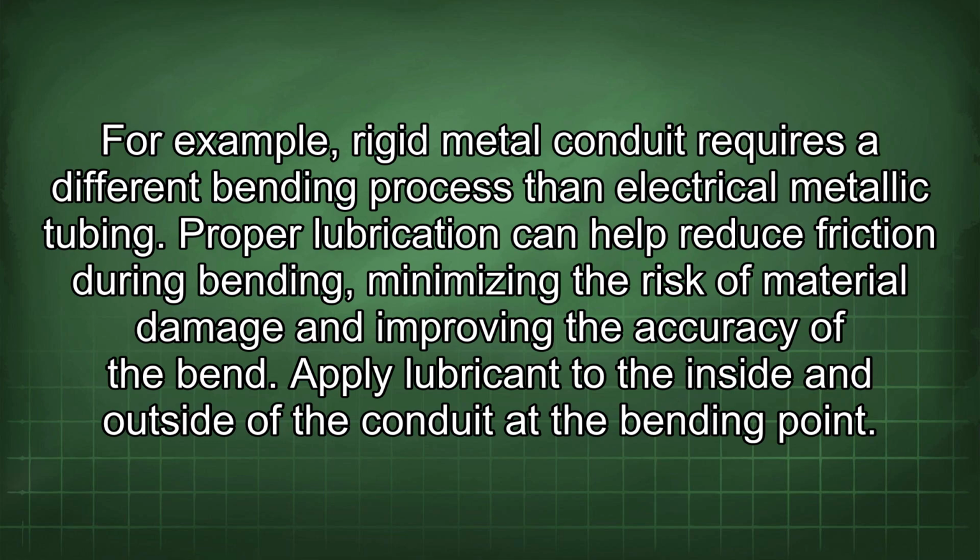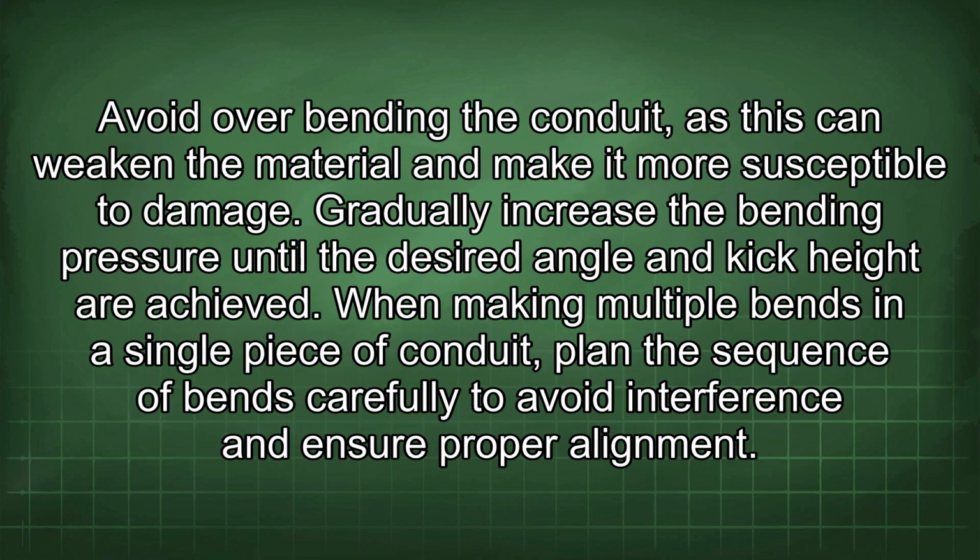Proper lubrication can help reduce friction during bending, minimizing the risk of material damage and improving the accuracy of the bend. Apply lubricant to the inside and outside of the conduit at the bending point. Avoid overbending the conduit, as this can weaken the material and make it more susceptible to damage. Gradually increase the bending pressure until the desired angle and kick height are achieved.